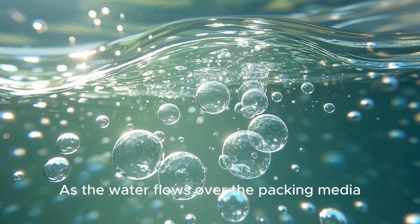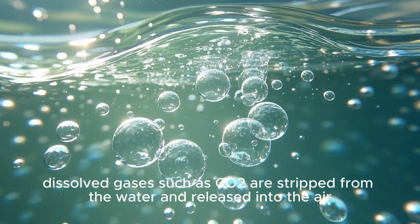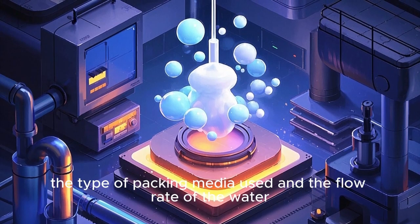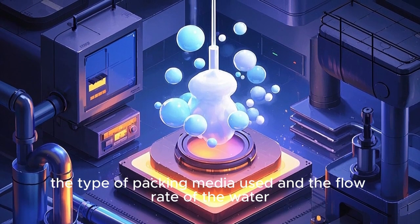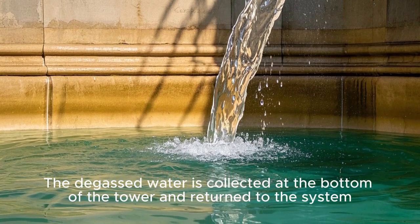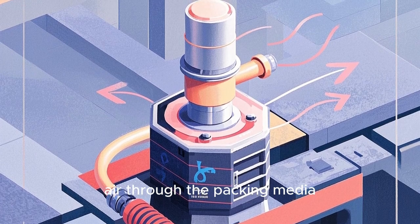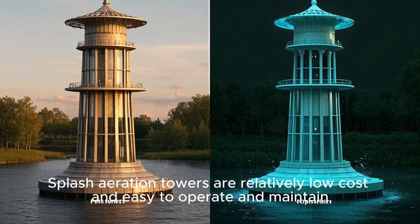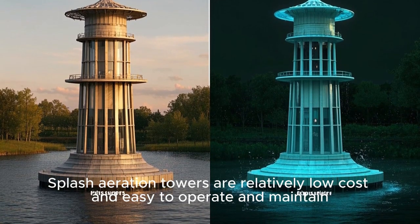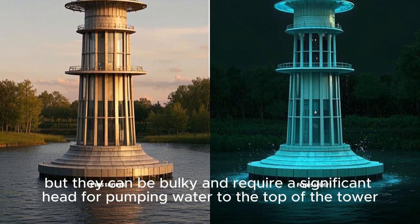As the water flows over the packing media, dissolved gases such as CO2 are stripped from the water and released into the air. The effectiveness of the system depends on the design of the tower, the type of packing media used, and the flow rate of the water. The degassed water is collected at the bottom of the tower and returned to the system. Some systems may also include an air blower to force air through the packing media, enhancing gas transfer. Splash aeration towers are relatively low cost and easy to operate and maintain, but they can be bulky and require a significant head for pumping water to the top of the tower.